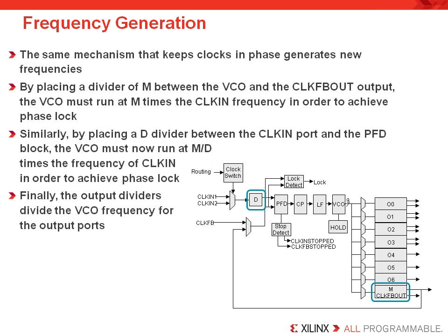So with the PLL, there are 3 counter attributes to set: the output, the divisor, and the multiplier. Now, generally, you would want the phase frequency detector, that's the PFD, to be as high as possible within a valid range specified from the datasheet. To accomplish this, you simply make the divisor as small as possible.